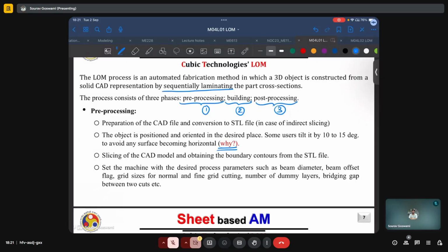Irrespective, however careful we are with the removal of these support structures, they always tend to leave remnants on the final built part, which affects the build quality, the surface finish, and the desired properties of the part. So a good practice is to minimize the number of horizontal surfaces.